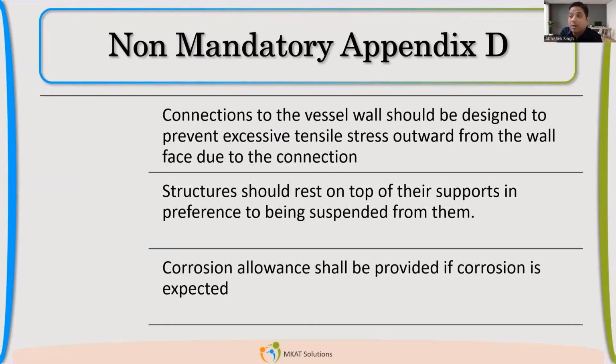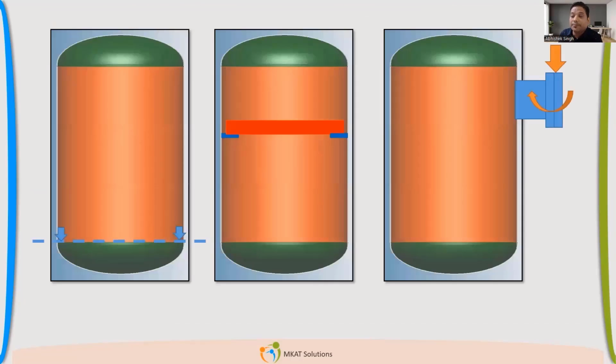Now how that happens: that is the reason we never directly weld the attachment or the internal to the pressure vessel. Because first of all, let us consider a very simple member which is supporting some other internal. Now, if we are welding it at both ends, there is no expansion allowed for this part, and it will behave differently than the vessel. So it will try to expand, and there is no provision for that. There will be additional stresses created.